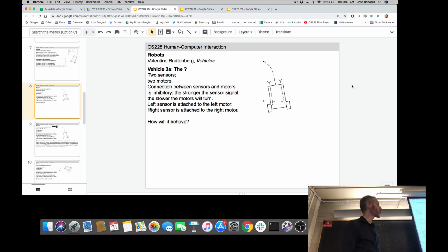Okay, so here's 3A, ipsilaterally inhibitory connections. Let's imagine that we forget the dotted line here. Let's say we add a light source here, front right of the robot. What is the robot going to do if it senses more light on its right than on its left? It's going to kind of chase it and be very standoff with it. It's going to make sure it's always looking at it, and then if it's straight on with it, it's going to play possum and not move.